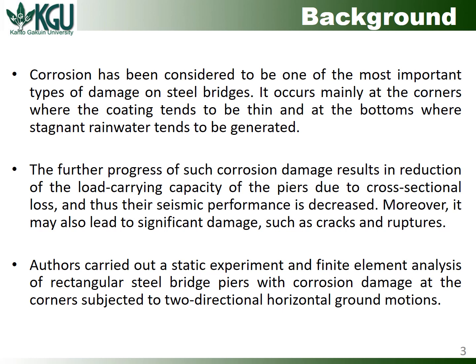The further progress of such corrosion damage results in reduction of the load carrying capacity of the piers due to cross-sectional loss, and thus their seismic performance is decreased. Moreover, it may also lead to significant damage such as cracks and ruptures.